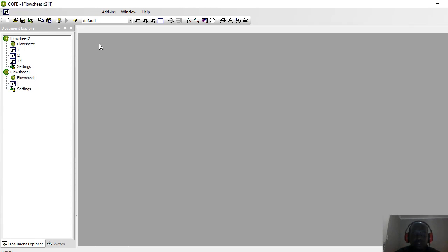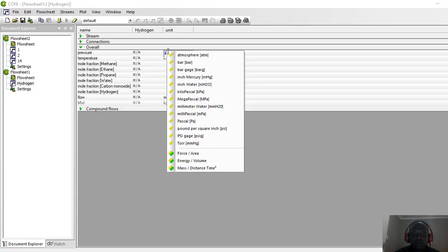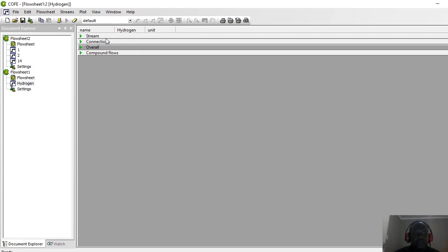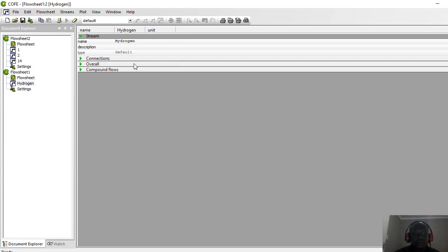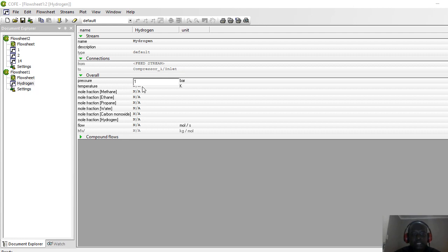Right? Hydrogen, we said we've got 0.24, so let's double click on that. The pressure, we can change that to bar, as we said, we're working with bars. And what we have here is 1 bar. These streams are coming in at 298.15 Kelvin, 25 degrees. We do not have any methane as yet.